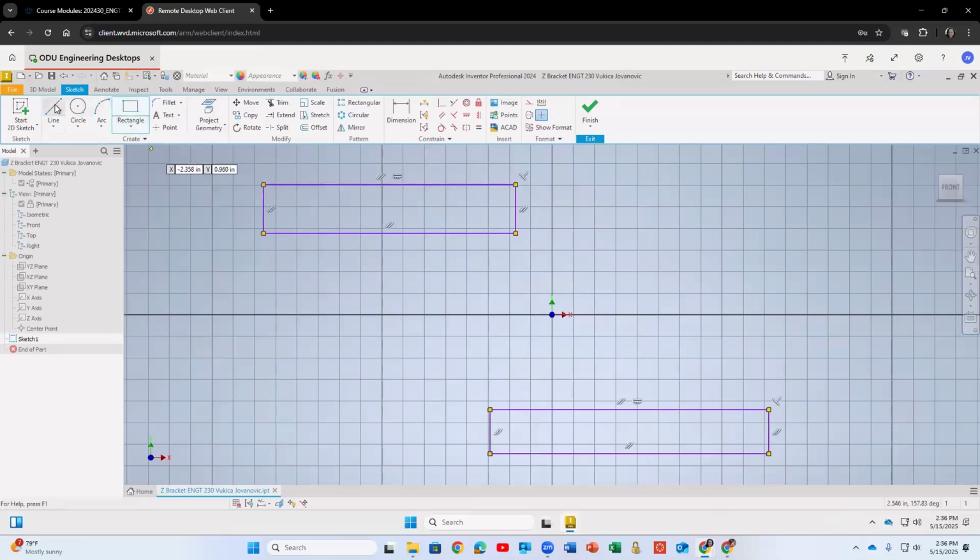And basically, you can trim this part, that part, and then you can just draw a line from one side above. Look, I'll go a little bit above. Escape. So again, left click on the line. I go here until I see this green thing, and then I can go down, and then I can just trim leftovers, you see, and align this.